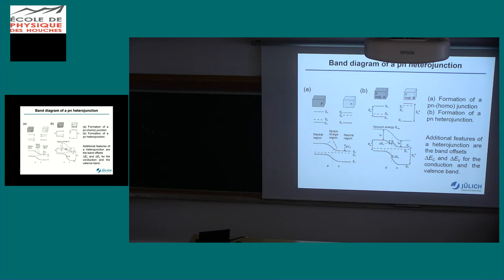That happens by bending things around, so that in the end this Fermi level, which is at different energy positions, gets flat, and then it's all the same as in the p-n junction. You get a plus space charge here, a minus space charge here. You can control the built-in voltage in a similar way by the doping of both ends. So that's not very much more complicated than just the p-n junction.